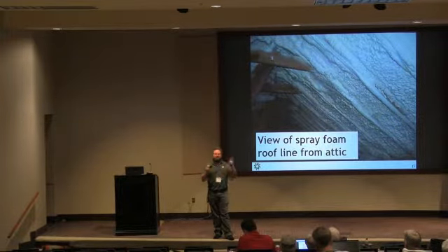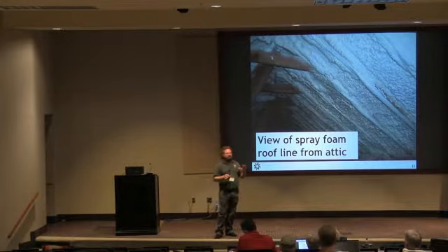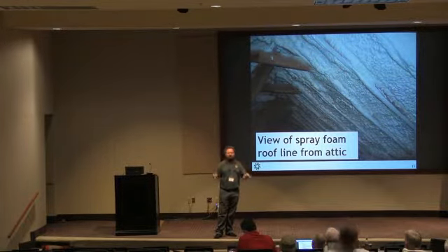They're the UV and they're the heat. And so if you want to do an unvented assembly, get a roof shingle manufacturer that warranties that. And honestly, if you're doing a retrofit and they've already foamed the house and then they need to re-roof, get a manufacturer that matches that.